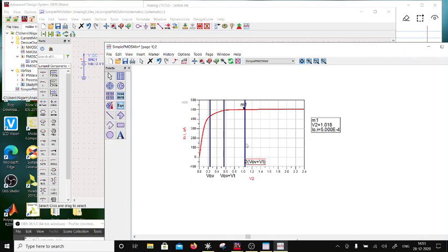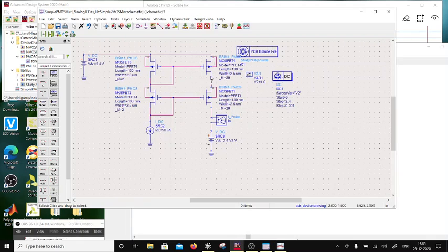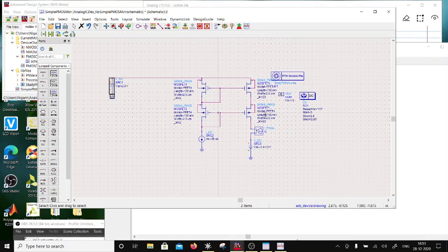So basically you can bring this down by a small number. Okay, Control C, Control V. You can make this do this over here, where instead of this you are going to see twice of V overdrive, but then this Vt comes out here like this. Okay, so you got rid of one Vt which you are dropping across this device. This is by forcing this voltage here to be V overdrive voltage.